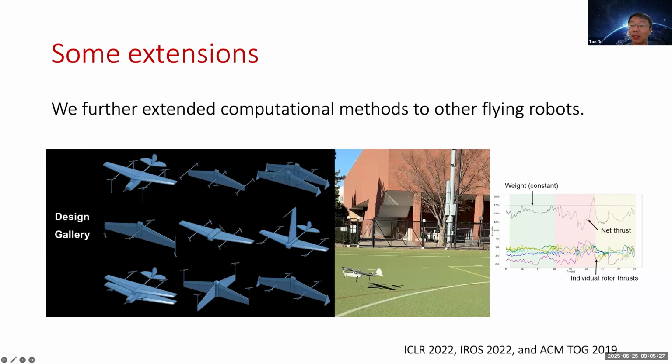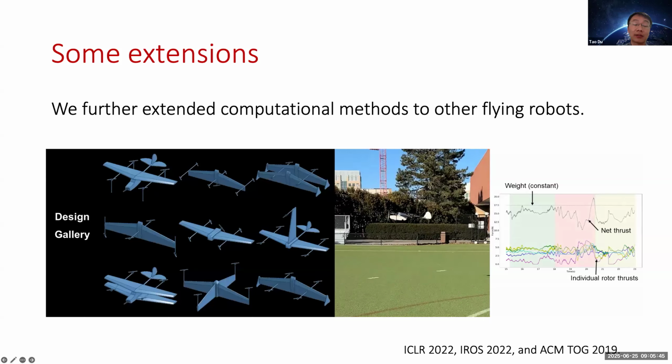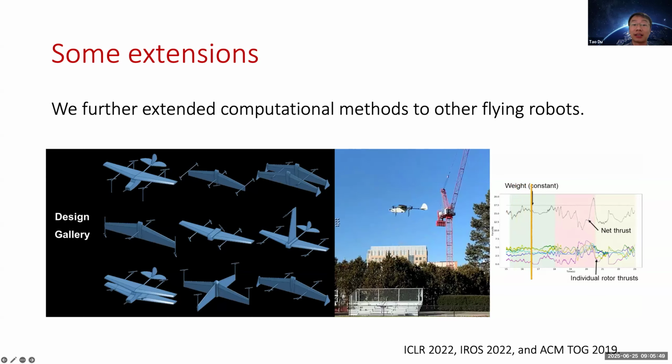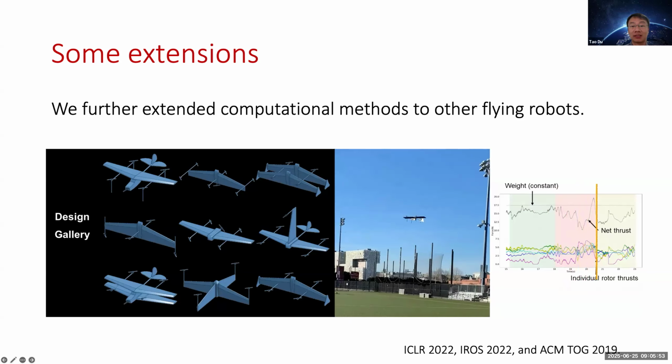The computational design pipeline here trained an end-to-end reinforcement learning controller that is directly deployable to the hardware prototype, which seamlessly exploits the benefits of both fixed wings and rotors whenever necessary. Here's a flight test taken from one particular instance of the design, which has 4 rotors and a pair of fixed wings.